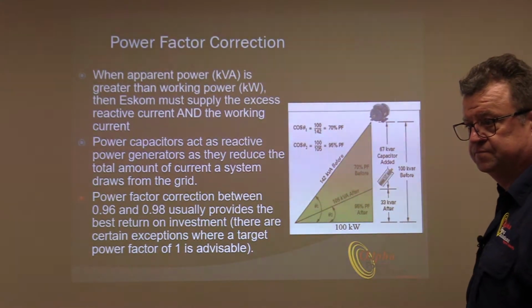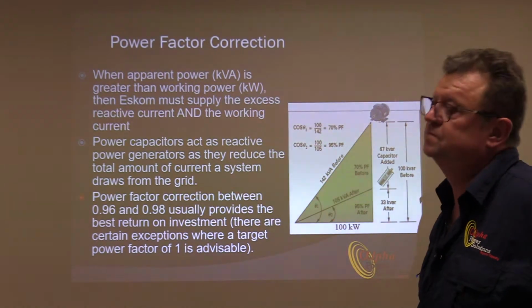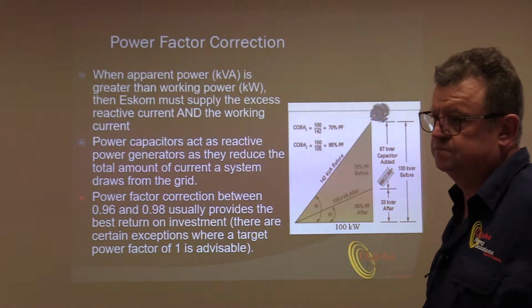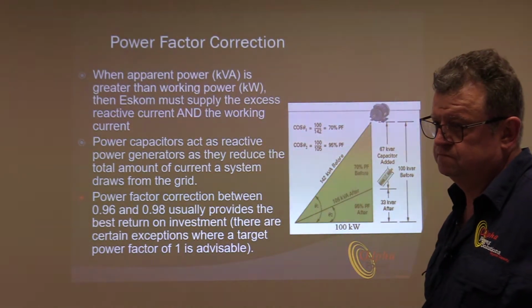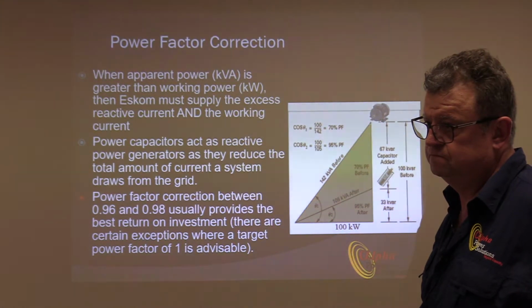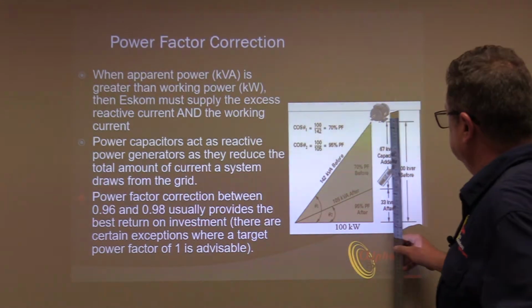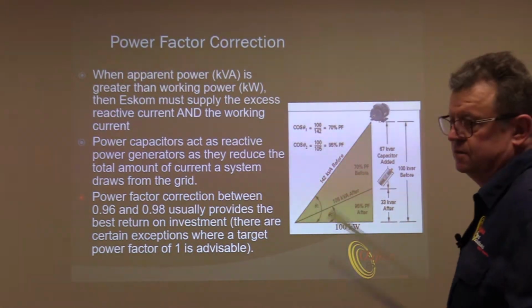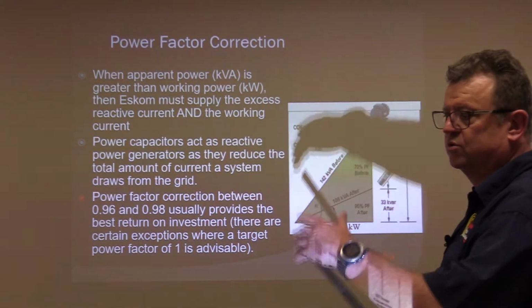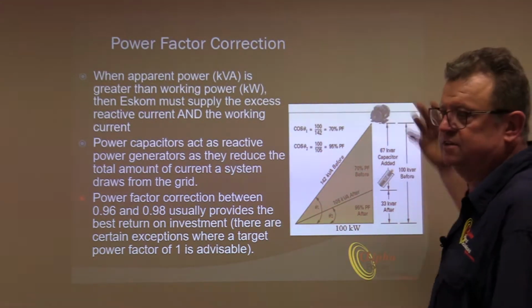So the demo unit that we looked at earlier, or the demo unit in the other video, showed us 3 steps. So what the demo unit would actually be measuring is what the kVAR is in order to determine which step to activate. Yeah. So the 67 would be broken up in 3 or 4 blocks. 20, 20, and 27 for argument's sake.